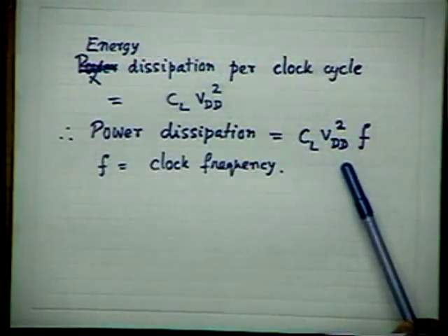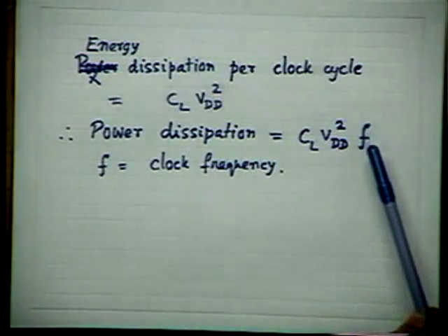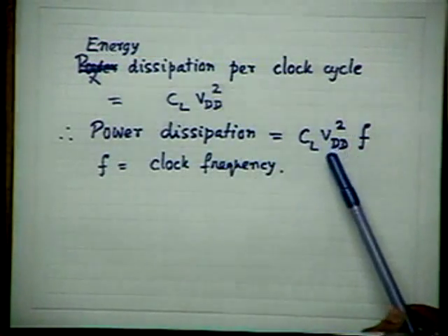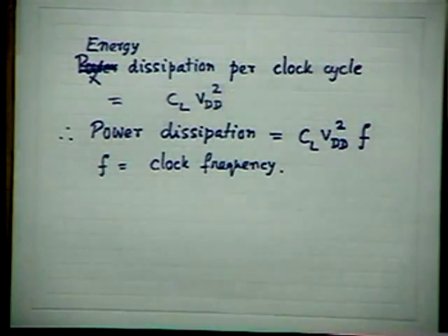Now, ultimately, you see that when you have to use a CMOS at a very high clock rate for the most advanced VLSI, as you know, nowadays people are designing and fabricating VLSI which is working at hundreds of megahertz, even gigabits per second. People are pursuing that clock rate. In that case, perhaps we have to reduce the power supply, because f is increasing too much. f will be a very, very important factor. Then to minimize power, supply voltage reduction is a very, very important thing to be considered.